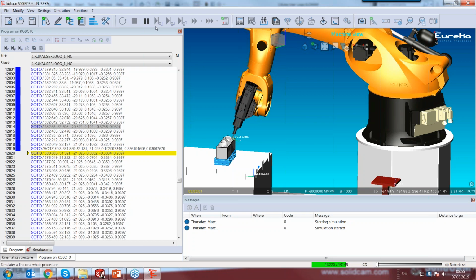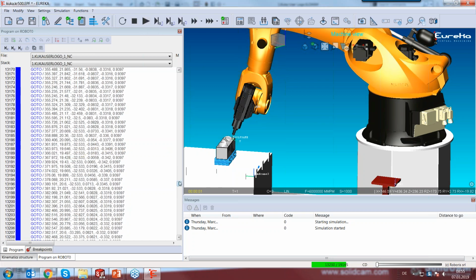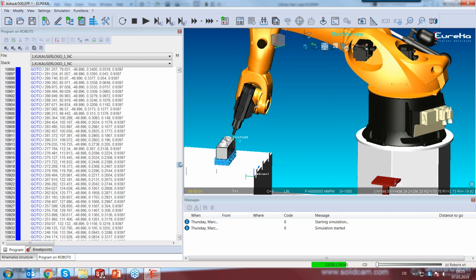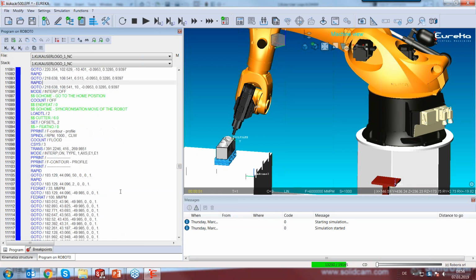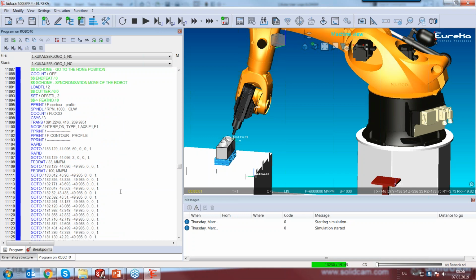So far, when I stop the simulation, I can go back to the first place of the operation. And that is what I said in the beginning. The robot moves from its last position and its last relation of the axis to the next point in the shortest distance mode in all the directions. So if we are going to change the initial position of the operation, the robot has a completely different behavior, because the first operation tells me a different point.